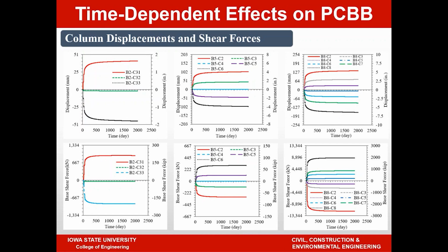So you could see clearly that if you look at the top displacements or base shear forces, these values are not constant between the columns. The extreme columns typically see much larger forces. Again, you can clearly see that as you get closer to the center, some of these columns see very small forces, and therefore they may not even be experiencing any cracking, as much as you see for the extreme cases where the cracking may take place in a matter of days.